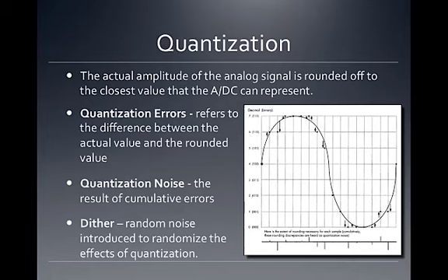Going from 24-bit to 16-bit is literally chopping off 8 bits of audio, and those 8 bits are really very soft sounds in the audio. So to mask the noise that gets introduced when we move from 24-bit to 16-bit, we can apply more noise. Kind of seems backwards, but